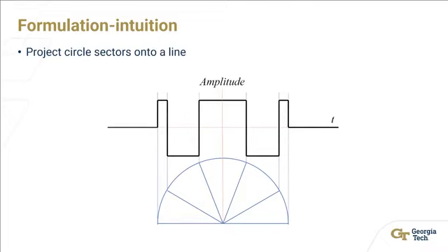To give an example of a higher order perfect pulse, shown here is a p4. There are a total of 4 internal transitions. Look how the pulse is symmetric about its center. Notice how the location of the transitions line up with a semicircle with radially spaced lines. This interesting geometry is the result of how perfect pulses are created.